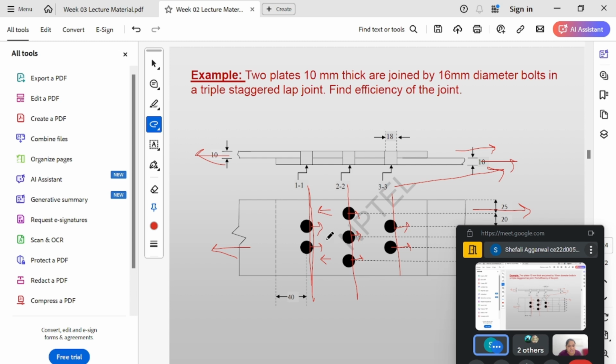Some reverse stress will be there, right? Yeah, definitely. So because of that we are considering the bolt value of these two bolts. My opinion is that it will be the resistance value of these two bolts, and in this case, the resistance value from these 5 bolts. So can I say that if the failure is passing through the second plane, there will be no situation where plane 2 fails without failing of the plane 1 bolts?